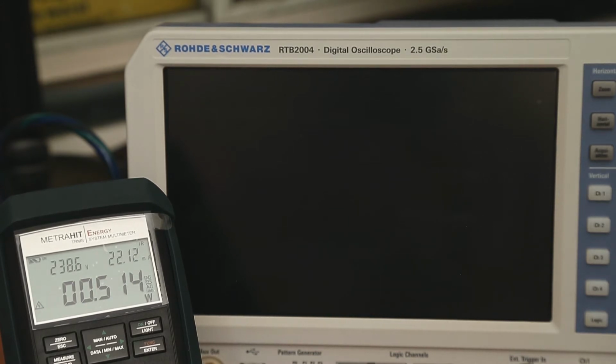So it's drawing now about 22 milliamps, which I presume purely is for the LED on the front. I'm not quite sure what else it would be running inside. I don't think the fan would be off now, etc. The 44 watts that this draws when it's running is fairly constant. It doesn't seem to change much with the fan coming on or off.